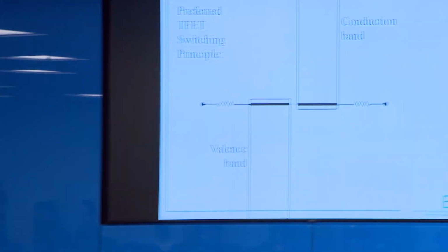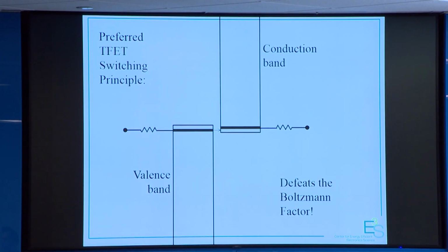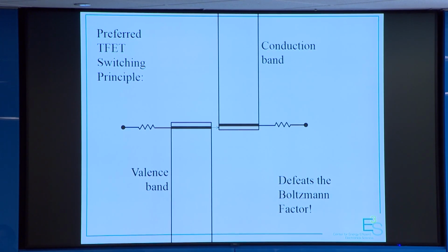but very interesting physics nonetheless. So with that buildup, say, okay, we want the whole thing. We want everything. We want a 1-to-1 replacement for the transistor. We want it to be made out of semiconductors, and how are we going to do that? So I already told you that we're going to do tunneling. Well, the tunneling is not that critical. What we're really doing is lining up 2 energy levels and then misaligning them, and that's it. And we've defeated the Boltzmann factor and potentially made a very sensitive device.